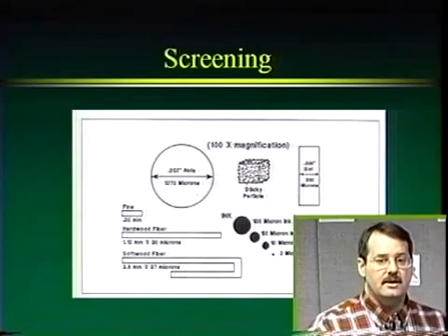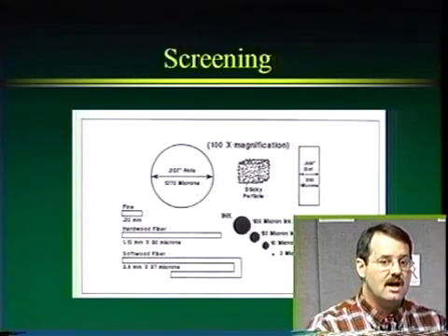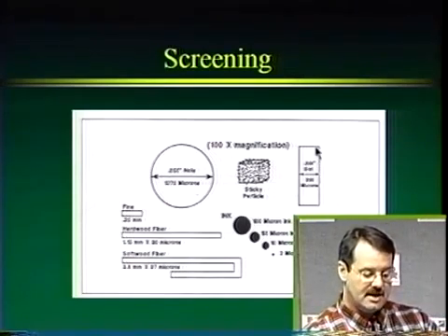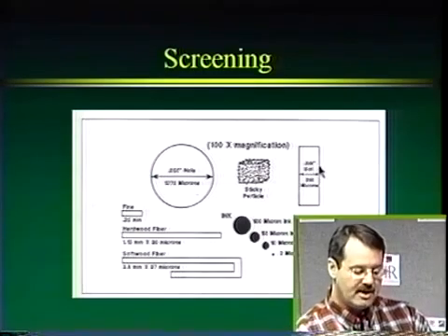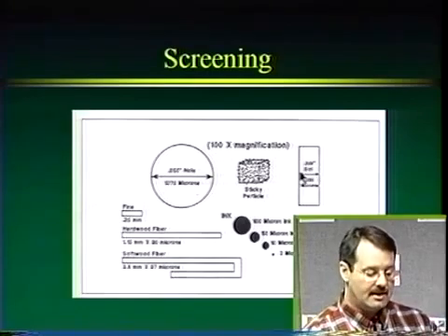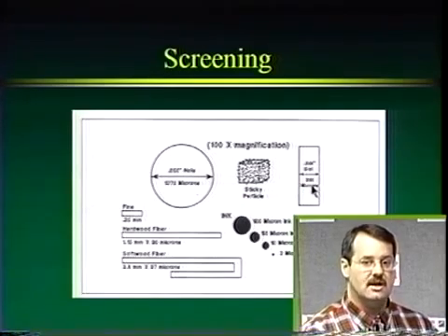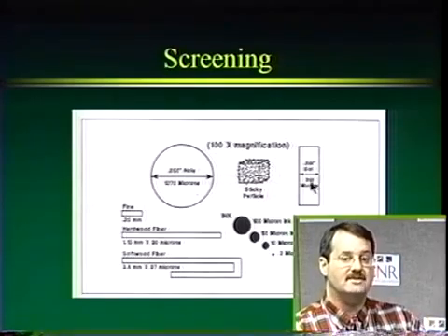This diagram right here shows some typical sizes of the slots or the holes that are used in screening. This rectangle right here corresponds to an 8/1000th of an inch slot. Oftentimes people call that an 8-cut slot. That's about 200 microns. And what we're interested in on this slide is looking and seeing what particles would be passed through.